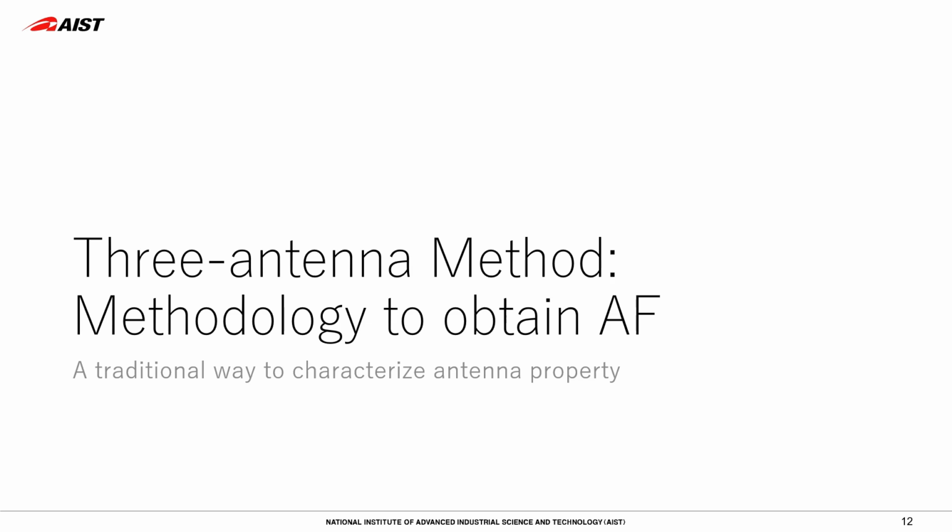Okay, from here, let's start some groundwork. The three-antenna method is a traditional method to obtain antenna factor and gain. It's a simple idea, but has a remarkable capability to implement. Although some difficulties remain in determining antenna separation, we can apply this method to many types of antennas.